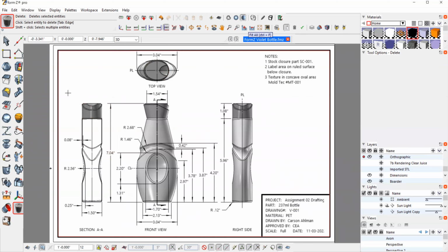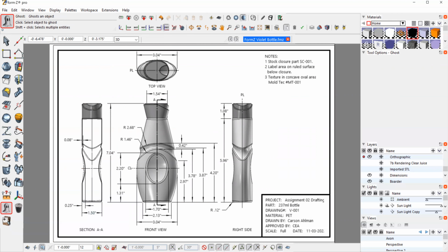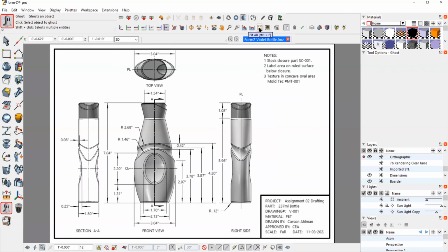And it doesn't. And I'll show you why. I have this little extra space over here. When I did this radius dimension, it automatically puts in its center point, which is that tiny little center point right on the edge there. And I can't get that to go away. So what I do to get this to work, I'll just ghost that dimension temporarily. I'll just ghost that and then go to fit. Now I'm perfectly set in that page in those dimensions. And then I can just unghost this. And I don't want that.